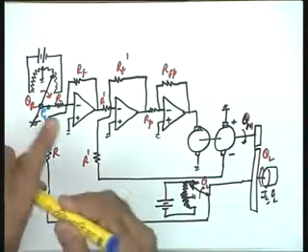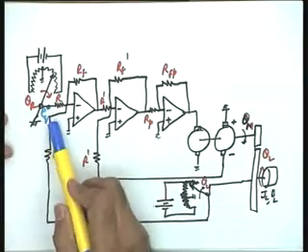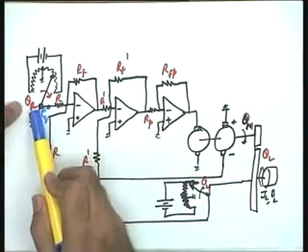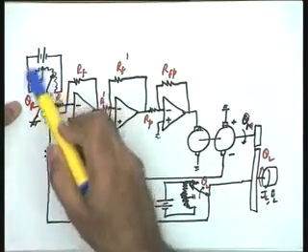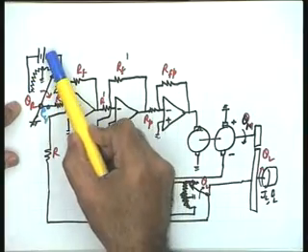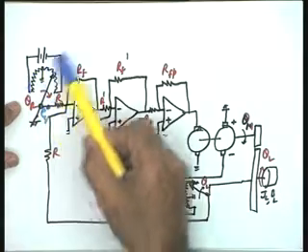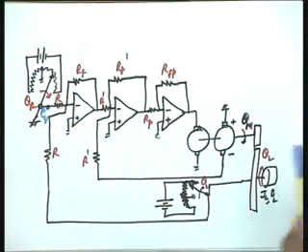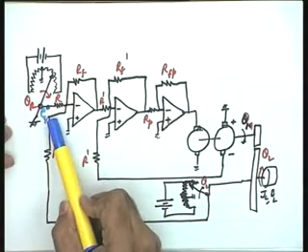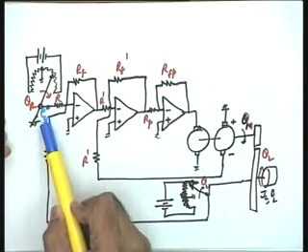So the relationship, you see, in your minor also these relationships were required. The relationship between ER and theta R is through a potentiometric constant, and that constant depends upon the voltage source over here, and upon the resistor used over here. But let us capture it in a single constant Kp, so that ER is equal to Kp into theta R, a voltage proportional to position is available.